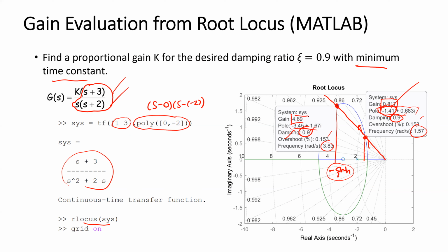But as I mentioned, when we compare the gain between K1 and K2, the locus moves from the first pole and hits the locus that comes from the second pole, and then goes up, goes down, and goes along the locus.